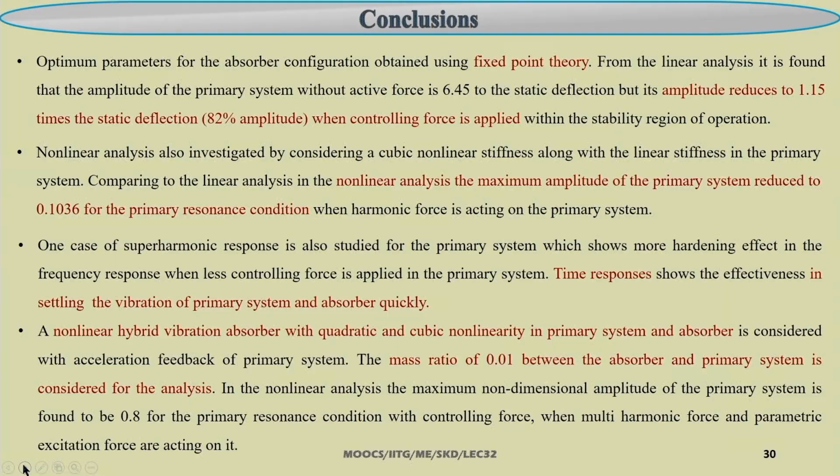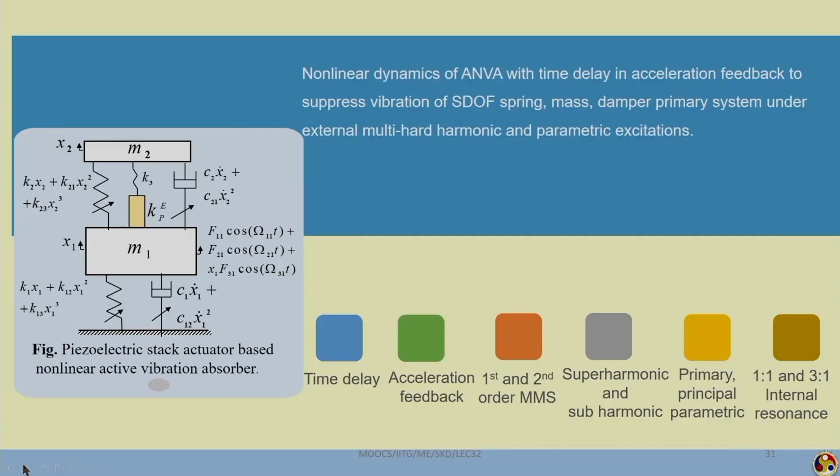By using this nonlinear analysis, you have seen we can control the vibration, or observe the vibration, with a nonlinear vibration observer by putting a mass 1 by 100 of that of the primary system. So, this is the advantage of using the nonlinear vibration observer.